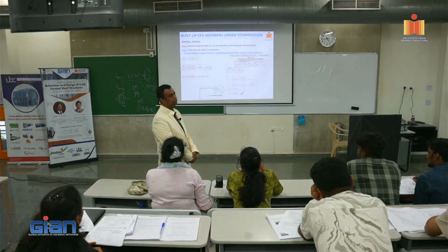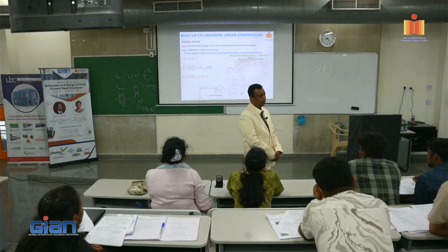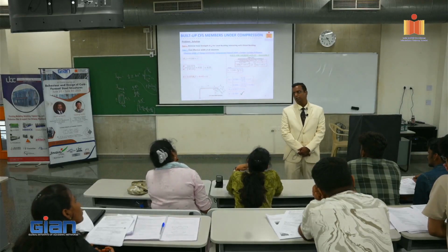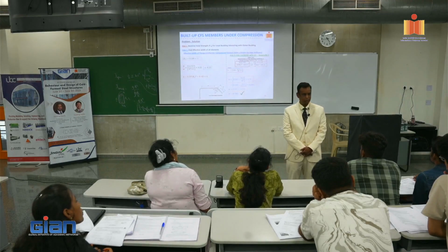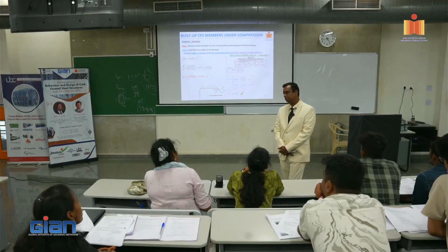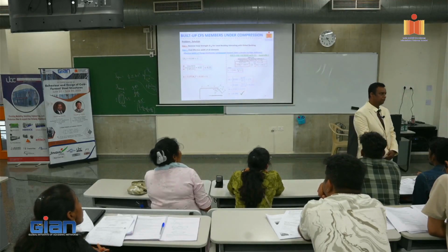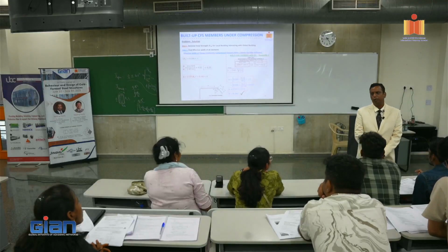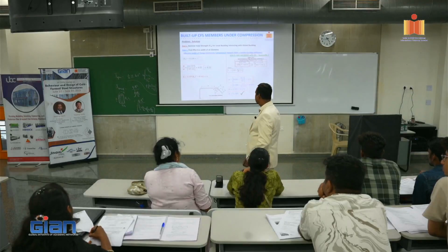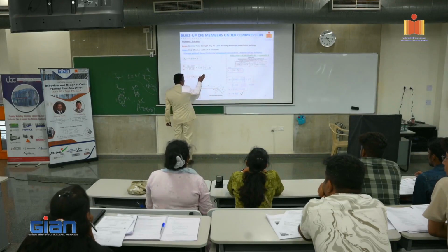Exactly. So not one end, 3 ends are simply supported and one end is free in a plate, right? But you usually take the 2 ends, loaded edges are simply supported, and then you take the unloaded edges as one side simply supported and one side free. If that is the case, you have K equal to 0.425. The code has rounded off to 0.43. So it says that the worst case, you will get 0.43.